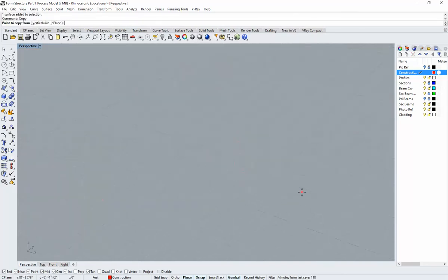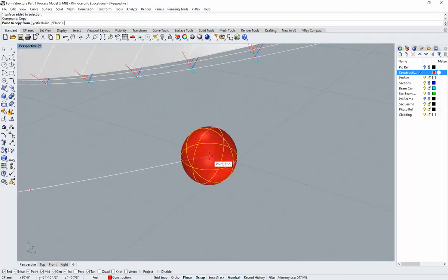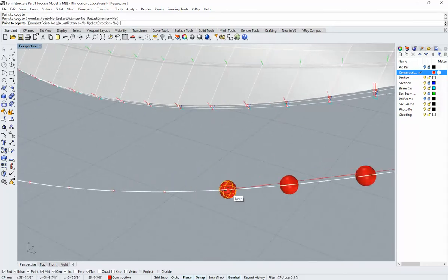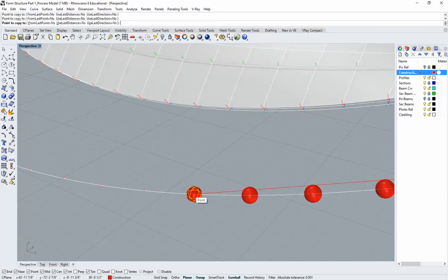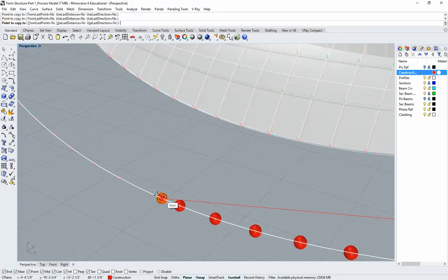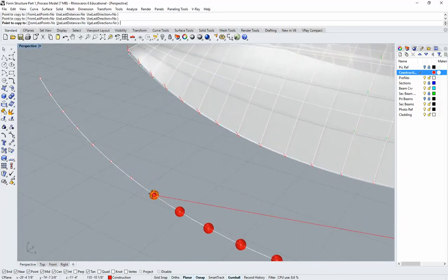Make sure it's not radius, make sure it's diameter, because that's going to be the distance. It's my offset, basically. It's 1 foot on either side of the center of the primary beams, or 2 feet on center apart is what those curved little bendy pieces are going to end up being. And I'm going to just copy the spheres across like this, and I'll show you why in just a second.